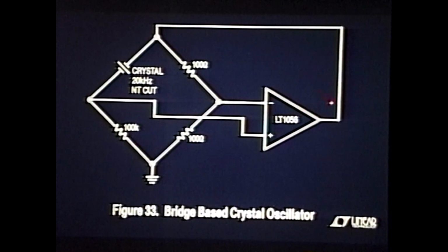But Meacham wasn't satisfied with that because he knew what he wanted was a high-quality sine wave with a low impedance output. He doesn't want this thing to go into saturation out here. He wants the gain to be such that in this nominally linear loop here, if there's a sine wave there, there should be a sine wave there, because nominally in a linear system, you want everything in phase.